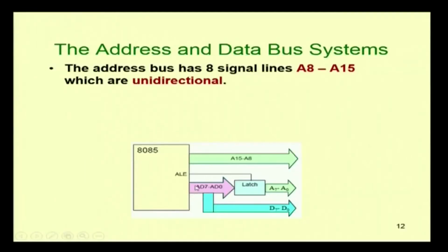That will make the size of the microprocessor larger, because so many pins means obviously the size will become large. So, what Intel has done is it uses multiplexing, that is, the same pin is used for address as well as data, as you see here. Although it requires 24 pins, address requires 16 pins, so it has got only 16 pins.